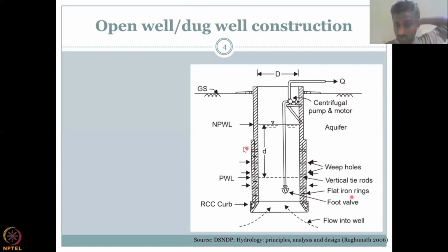All we need to see is how does water move? Water moves laterally and also from the bottom of the well. It just comes from the bottom up, depending on the pressure difference. So make sure you understand that there are multiple pathways through which water comes, and when the pump is turned on, most of the time the foot valve is open at the bottom, or it can be screened like your panel. You can have a screen in the pumping tube, and water can come through.